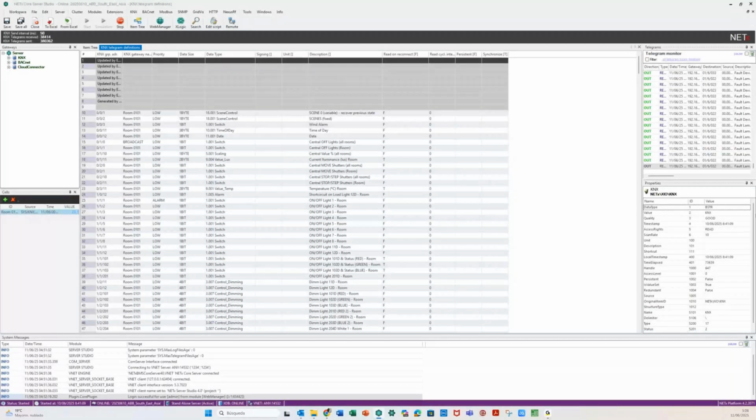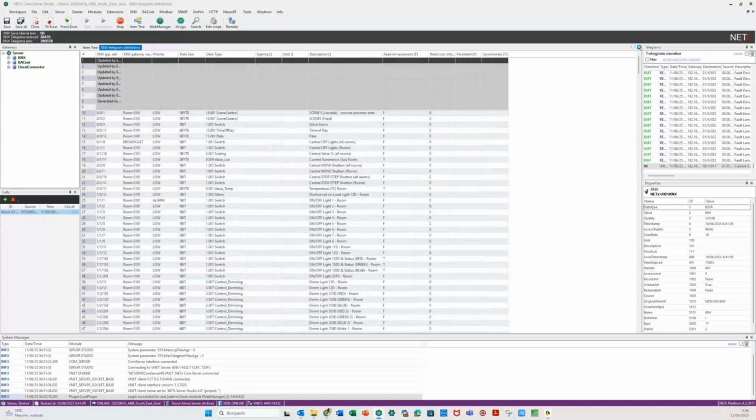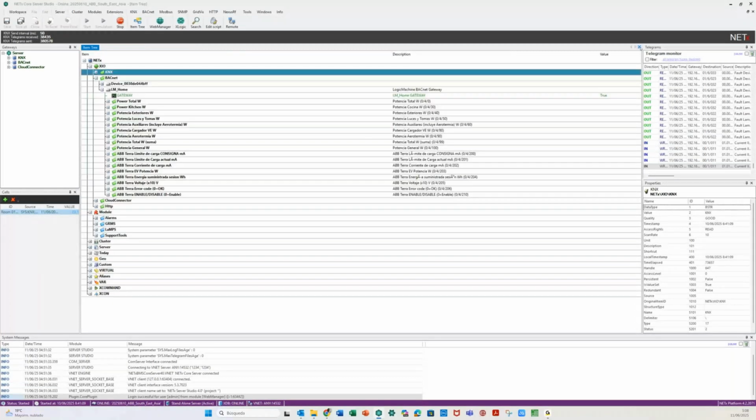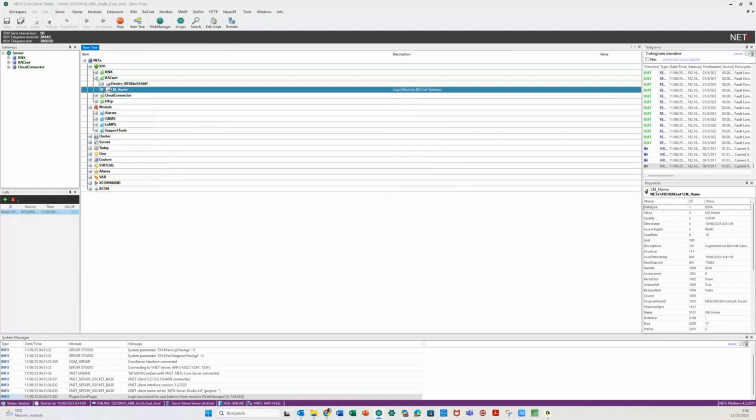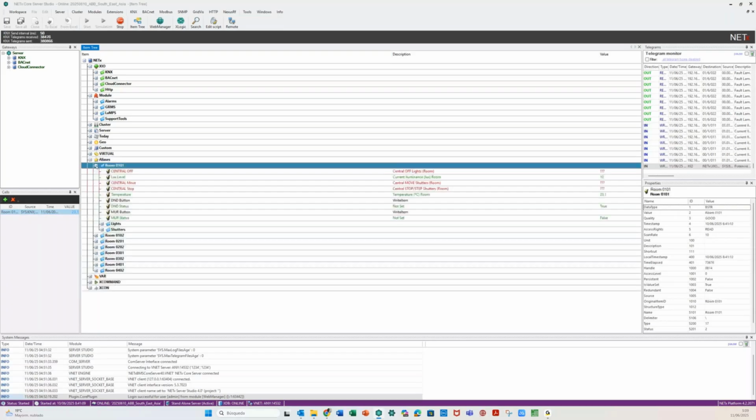And in terms of BACnet, again, we have devices and objects. We didn't have enough time to explain everything, but a slight view of what we have to do to integrate these protocols was explained yesterday. So we have a lot of data points, but the problem we faced was that each data point has an item ID. So how do we mix KNX and BACnet, for example, for the same room in an office or hotel or whatever? Then we explained how to organize everything into aliases. This was the last thing we explained: using the alias management.